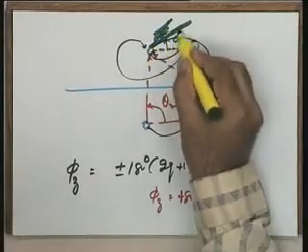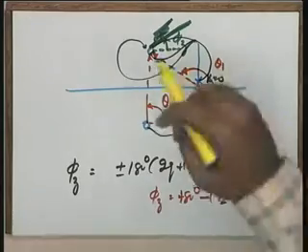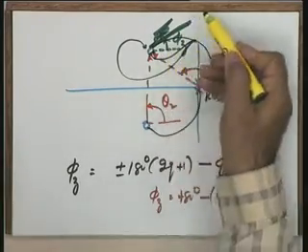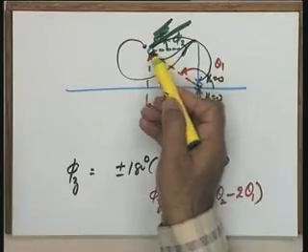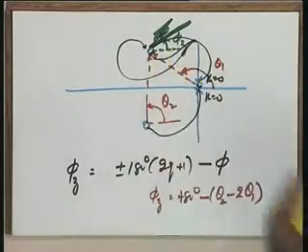This is phi z. If it approaches the way I had drawn earlier, if it really approaches through this particular way, then the phi z, the angle at which it approaches the origin, approaches the complex 0, is given by this particular direction. So, this becomes the angle at which the root locus branch approaches a complex 0.